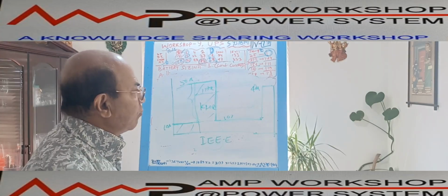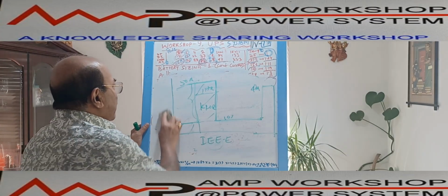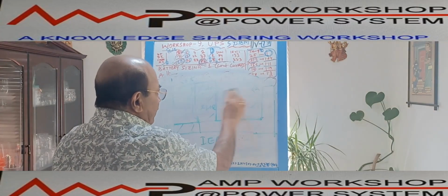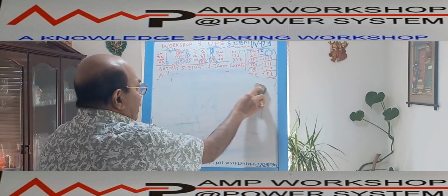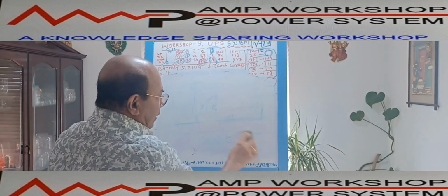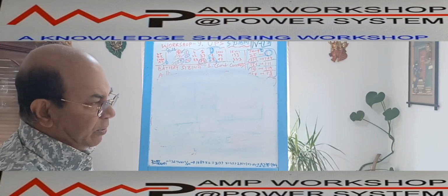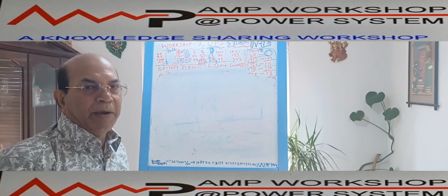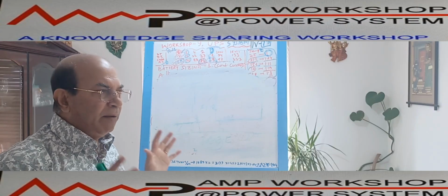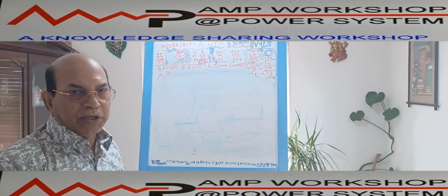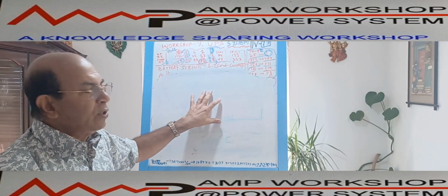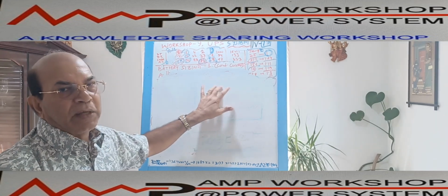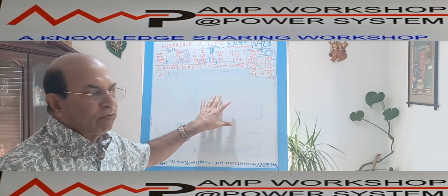Second, another part we have to mention over here. In the case of the UPS calculation, we have done the calculation based on the load, but we have not separately calculated the inverter capacity or rectifier capacity. For rectifier capacity determination, we have left things with the manufacturer, because the manufacturer will deliver the battery and knows the intermediate voltage if there is no other load connected to the DC.